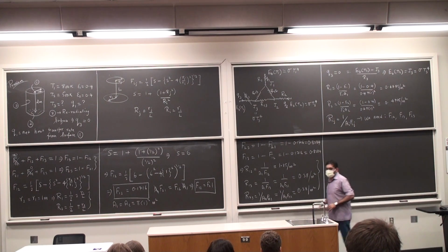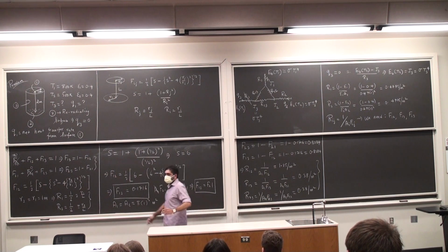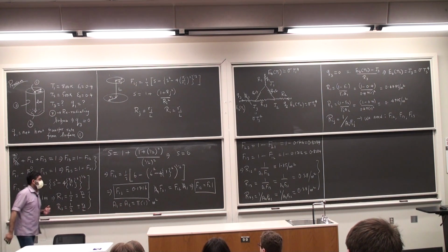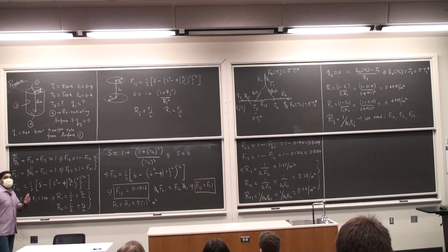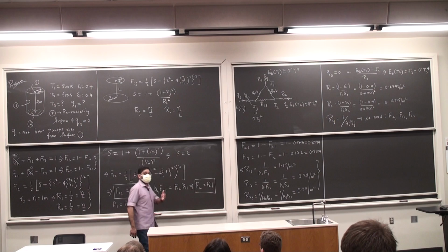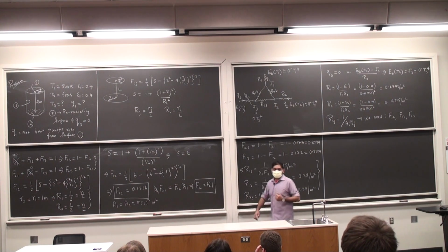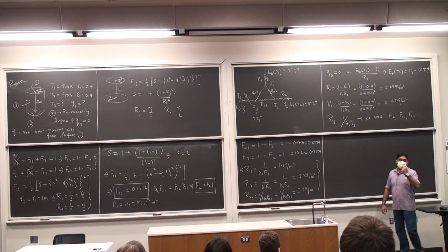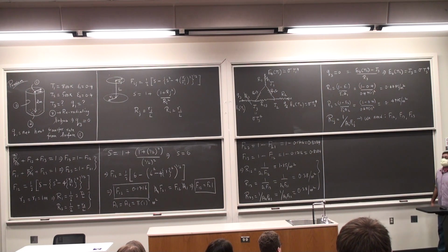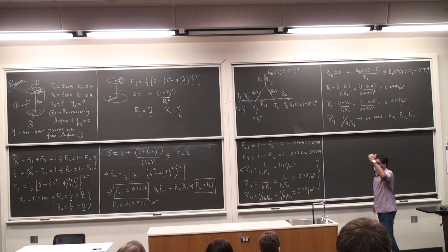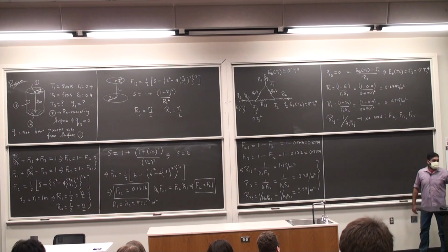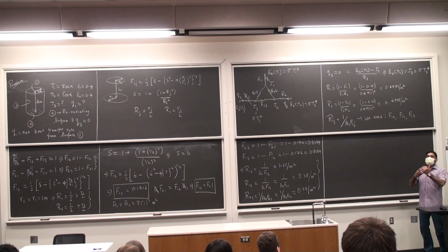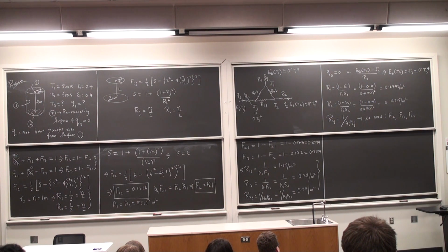So we have everything good to go now. We have the resistances calculated. We have the network drawn. All I have to do is apply Kirchhoff's laws for electrical networks. We have already applied Kirchhoff's law for radiative systems by saying, okay, diffuse gray surface, epsilon and alpha are the same. And based on that is actually how we came up with this resistance network. And it's really a thing of beauty that Kirchhoff came up with the electrical network idea. His laws resulted in the thermal network idea as well. And there is this confluence of these two disparate ideas into one nice tool for us as engineers. Okay?